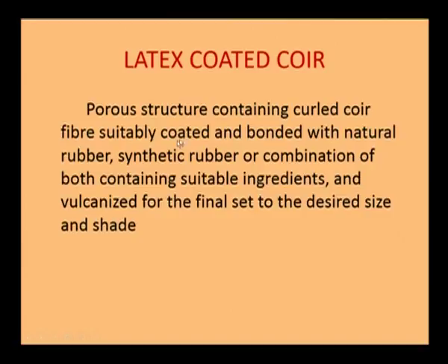Coir is nothing but the fiber which is taken out from coconut. So, you take the coconut shell and you take out all the outer skin, that is the fiber which is present in the coconut, and you use it for making various valuable products. Latex coated coir is a porous structure containing curled coir fiber suitably coated and bonded with natural rubber, synthetic rubber, or a combination of both, containing suitable ingredients and vulcanized for final set to a desired size and shape.